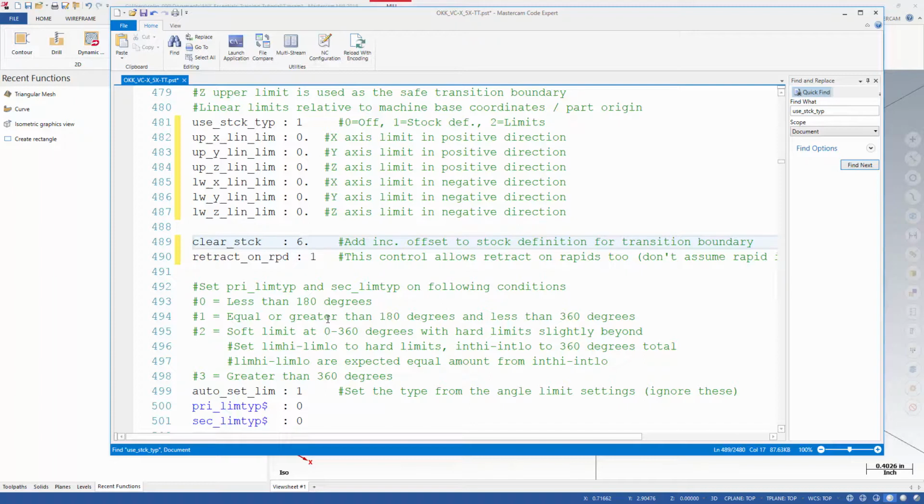So if you want to use that safety zone and you want to do a 3-axis style toolpath, you should check out the triangle mesh toolpaths, because you can do a 3-axis style path. You can get all of the retract motion you want, and you only have to worry about the null tool change, retract, and approach. And null tool change, retract, and approach is different than a reposition in the middle of the path.